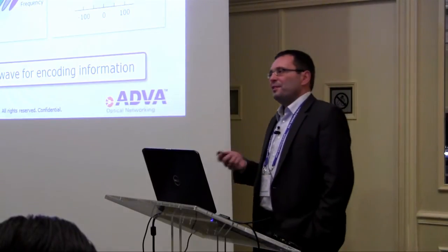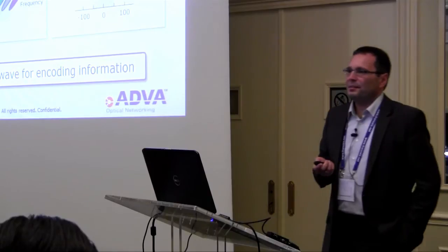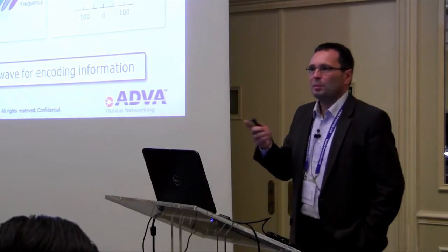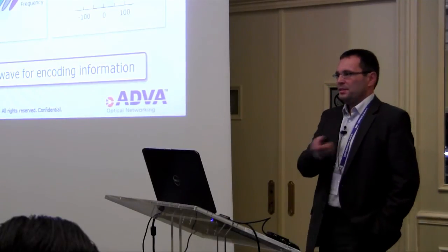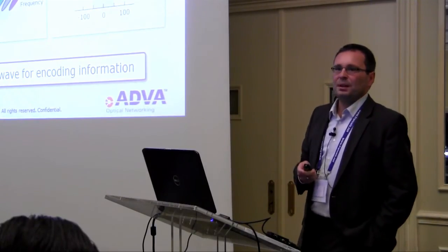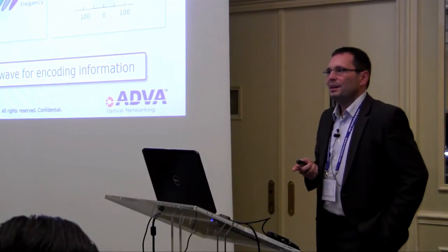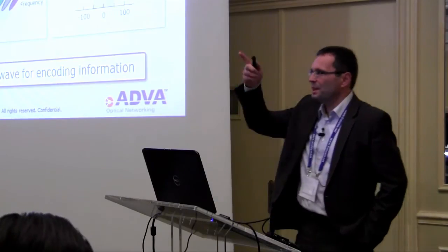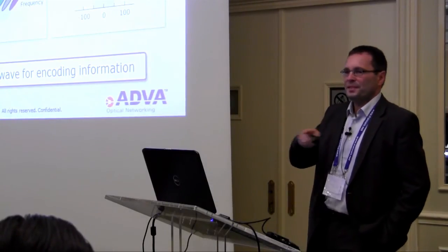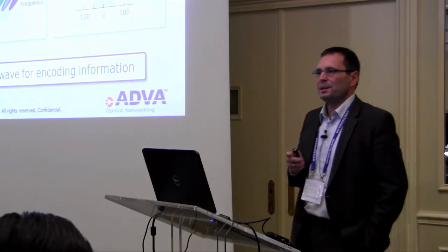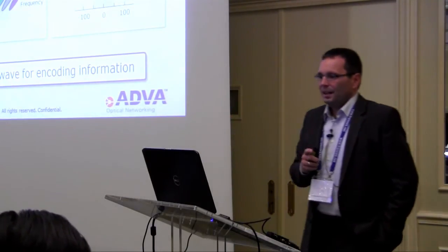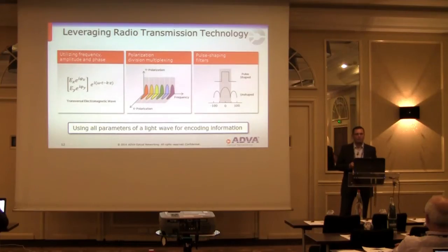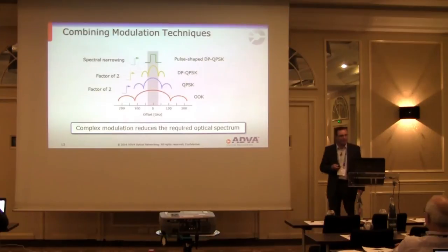We can talk about different things like polarization multiplexing, a very easy thing. If we send a light signal through a fiber, then it has all the polarizations if we do nothing. So it oscillates like this, so you can't read a lot from the polarization. But you can filter it, and you can use 2 dimensions. You can use vertical polarization, so it oscillates only up and down, and horizontal. And suddenly, we have 2 signals already on 1 wavelength. And then we use some pulse shaping filters in order to make it a little bit sharper. So we are using a lot of different things, and we will learn how we do that.